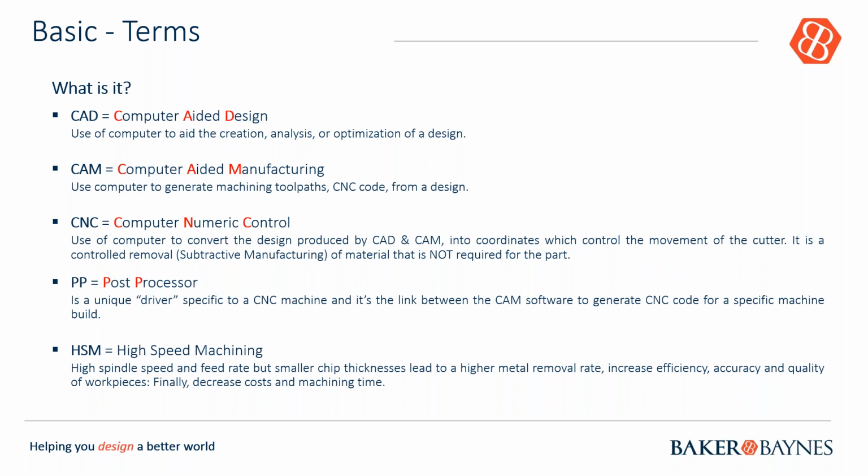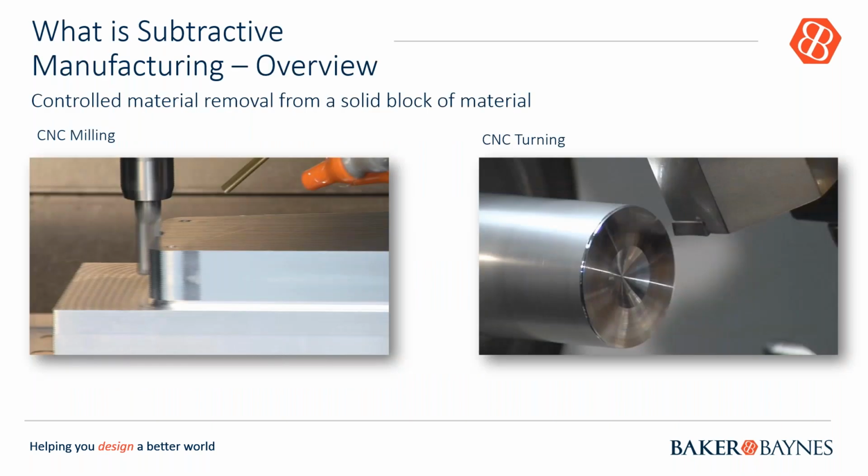Here you find water jet, and with water jet the accuracy is quite high, and sometimes the thickness is quite high as well. Plasma cutting has medium accuracy, as you can see there, but you cannot go too thick with the material that you're cutting. Laser cutting, the accuracy is quite high, but the thickness is low, so you've got to maintain a specific thickness on that.